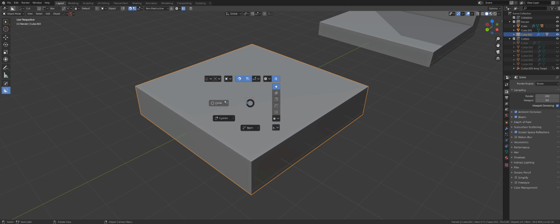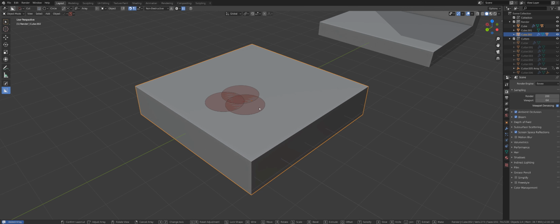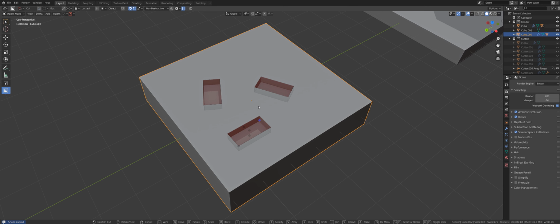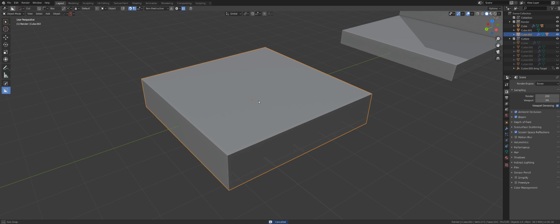Now remember when we were drawing the circle and pressing V twice for the array? Well, you can do the same thing with boxes. The problem is that if you click on array with boxes, you see that they're sort of misaligned, which could create an interesting pattern on its own. However, if you want it properly aligned, during the draw, if you hold Alt, it's going to draw from the middle.